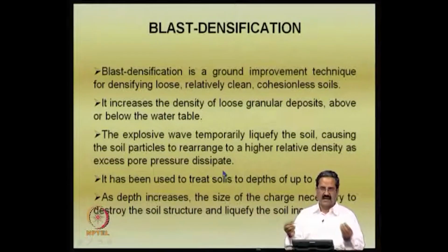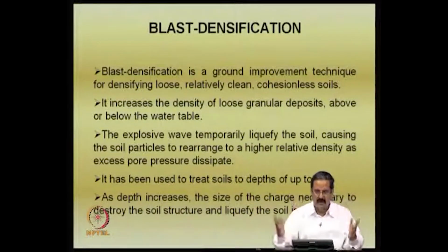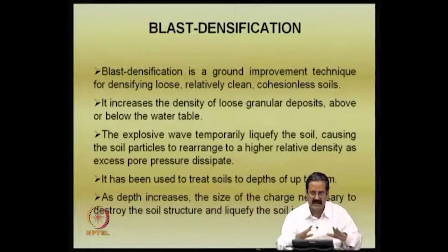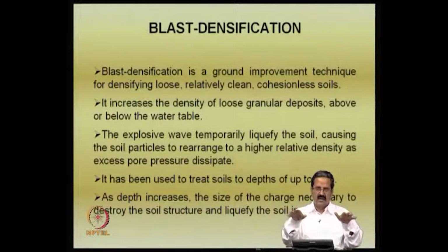You must have seen the case of a sand boil, in which liquefaction occurs, then there is a settlement of the ground, and then the pore pressure comes out. Once the pore pressure comes out, that area is slightly densified, so the excess pore pressures are dissipated. We have done this sort of experiment in the lab, where there is a saturated soil mass with a loose density, and if a bit of vibration is applied, then there is a settlement, and the water table is at the top. So you can see that there is a water table.